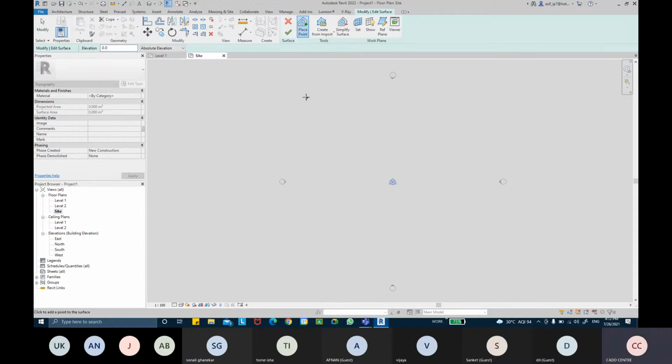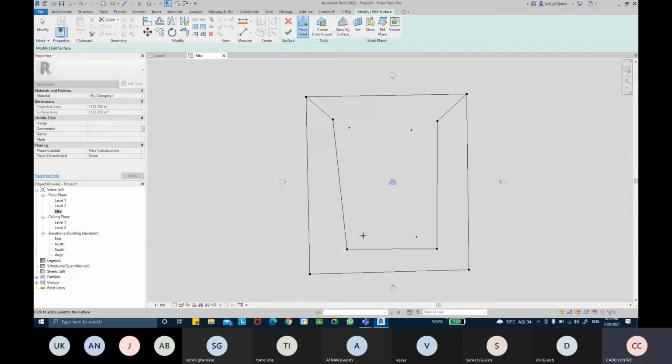I'm going to set the elevation point as 0 elevation. I'm going to create 4 points, 1, 2, 3, and 4. I'm going to create a couple more points over here in the middle, like that. These are also at the same 0 elevation height. Then I'll drop it into minus. So I'm going to take it as minus, a little bit deeper, 3 meters. Great. Points here, here, here, and here. Okay, 4 points created, and you can hit Finish mode to complete.